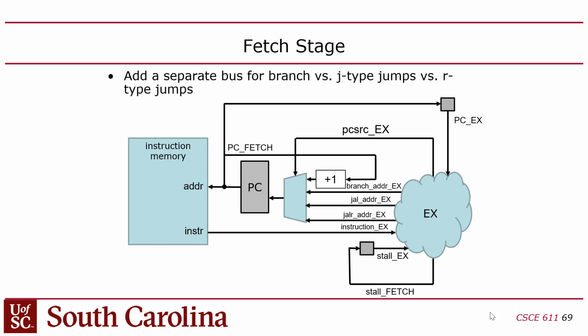So that means that you have to save which program counter you want to save, so this is where it gets weird because the branch is in execute. The link address is in fetch when the branch is in execute. So when the jump and link is in execute, I should say jump and link, because branches don't link.